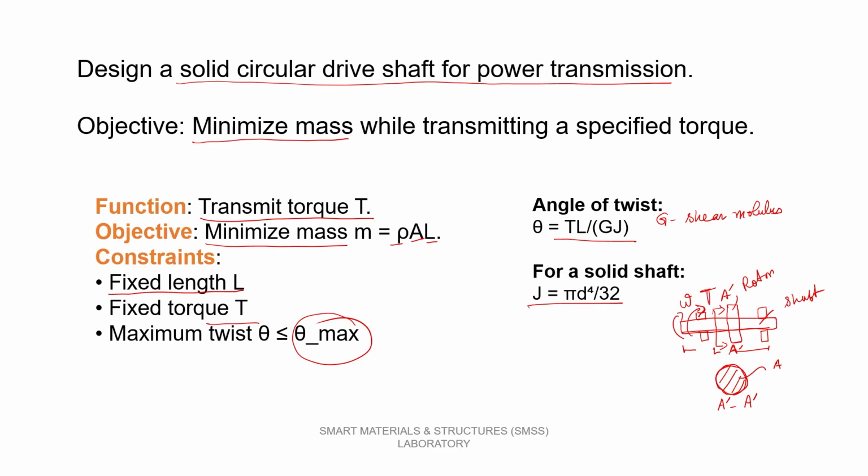So, let us go to the next slide and see how we can use this information in terms of the material property index selection. Well, one thing we have to keep in mind is that we have to have a free variable. Okay. Now, that free variable can be the area itself, but more realistic in the case of a shaft is the diameter of the shaft. Okay.